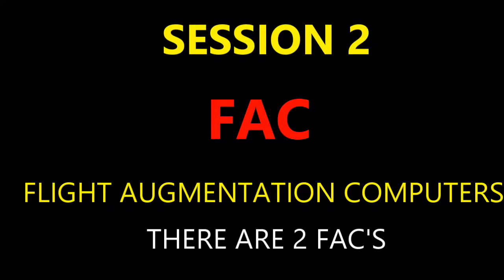Now, there are 2 yaw dampers, and in normal operation, those are engaged. But you're going to have one that's active. So there's a difference between being engaged and being active. Your yaw damper 1 is the main one, and its operation involves different components. Obviously the flight augmentation computers, but you also have 2 rotary variable differential transducers. You also have your actuator with different components, your servo valves, a pressure switch, that kind of thing. And then you also have 2 electrohydraulic actuators. Those actuators have subcomponents, such as the valves and of course the transducer. You get linear variable on that one.